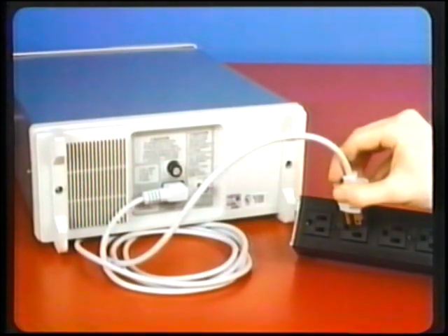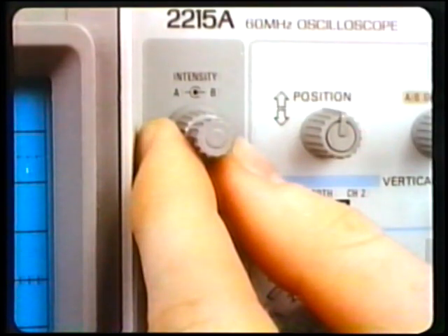The first step is to connect the power cord, located at the rear of the unit, to an AC outlet supplying 110 to 120 volts at 60 hertz. The A and B intensity controls located in the first block adjust the brilliance of the displayed waveform. Before turning on the oscilloscope, be sure to set these controls to their minimum positions by rotating them both counterclockwise. This must be done to protect the screen from damage due to an overbright display, which may cause discoloration or burning of the screen.